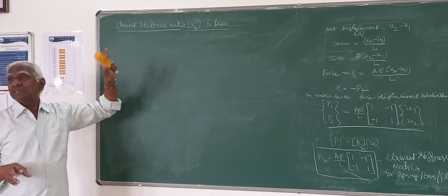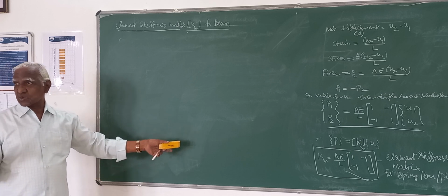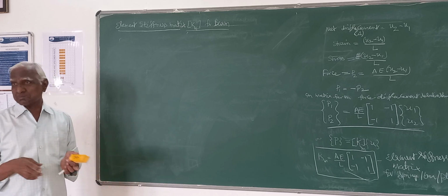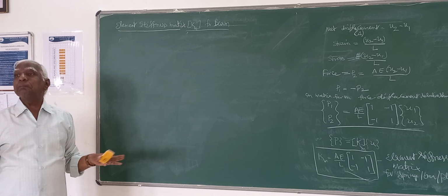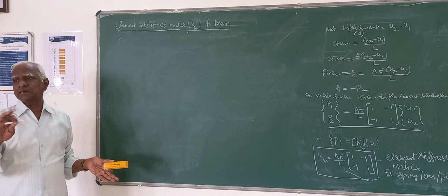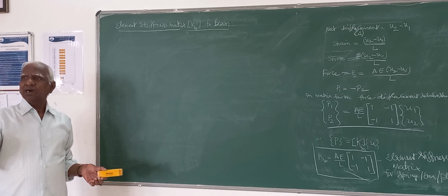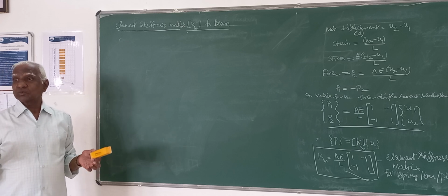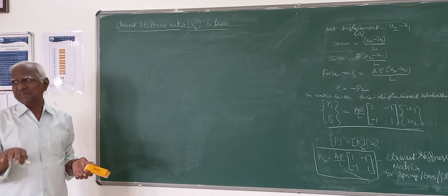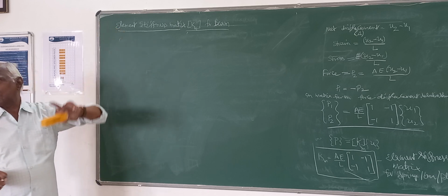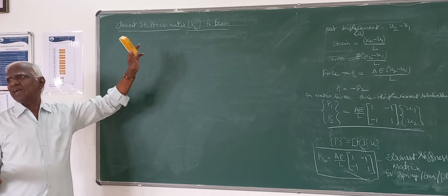So this stiffness method is the one which is widely used in the analysis. That is the reason I have indicated why we go for only the stiffness method, because it always deals with unknown displacements which are mainly independent in nature. It gives a relationship, and forces can be easily found. In flexibility, it depends on the unknown forces, but unknown forces need not always be independent. So it becomes very difficult to decide which ones are independent. That selection itself becomes a tricky issue. So that is why this is widely useful. I have told the advantages of stiffness method and flexibility here itself.